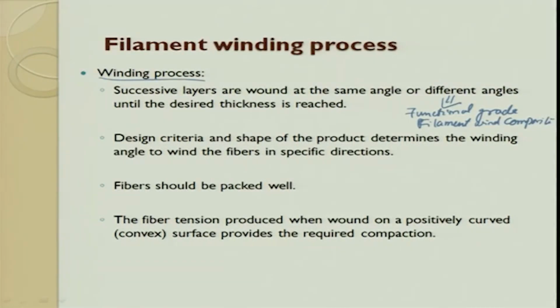Why is it very important? Because see, many a times what happens, we do near net shape manufacturing through these composites, and after you make these composites you have to assemble these composites. When you try to assemble these composites, you have to drill. The moment you have to drill, then what happens, the thrust force, when it is acting on the component, the thrust force has to be uniformly distributed. So, that distribution can be done if you use different angles. So, that is one way, plus depending upon your mechanical requirements you can do.